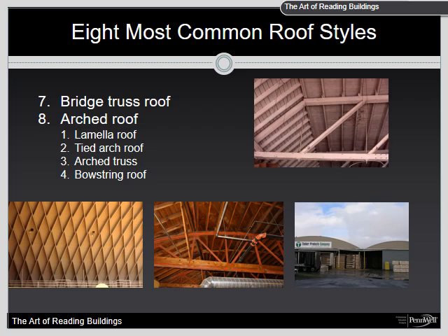Early bowstring truss roofs used large dimensioned timbers for cords, along with iron plates and bolt fasteners. A substantial roof. Likewise, the Hammond all-iron riveted bowstring truss is considered the high water mark for bowstring truss strength. The bowstring truss made from smaller dimension wood, all steel, or steel-wood combinations typically requires pilasters or buttresses on exterior walls to help absorb lateral forces.